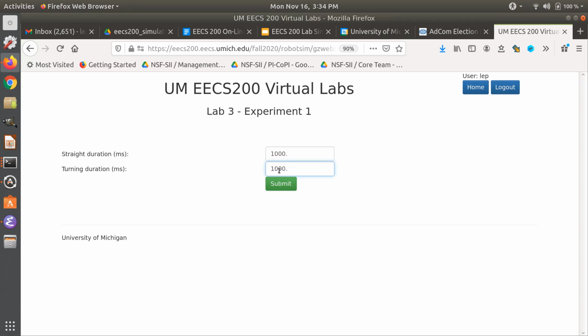What I don't tell them is that this is pretty much impossible to do open loop, because the motors have various inconsistencies. No motor is the same as the other motor, and they vary a little bit in time as well. And so when you tell them both motors to do the same thing, they don't do the same thing. And so the robot turns, because all we have is two wheels.